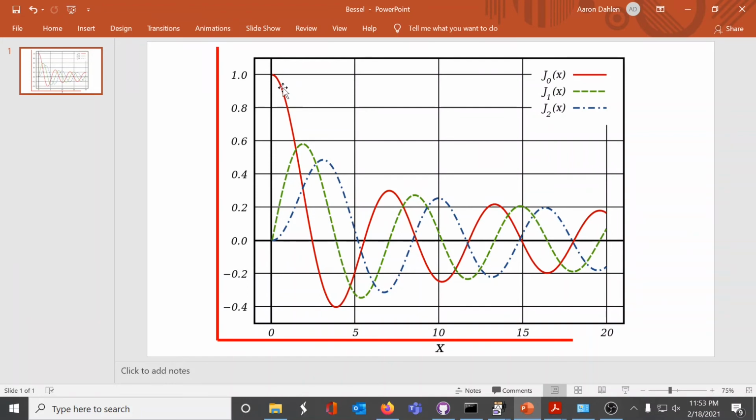This line in red represents the carrier. The line in green, that's this one here, represents the first sideband pair. This line in blue represents the second sideband pair. So carrier, first sideband pair, second sideband pair. This is a good time to consult your textbook, where you'll see that there are additional sideband pairs. But for simplicity, I thought this was a good representation. You'll also find the data in tabular form, which might make things a little bit easier.